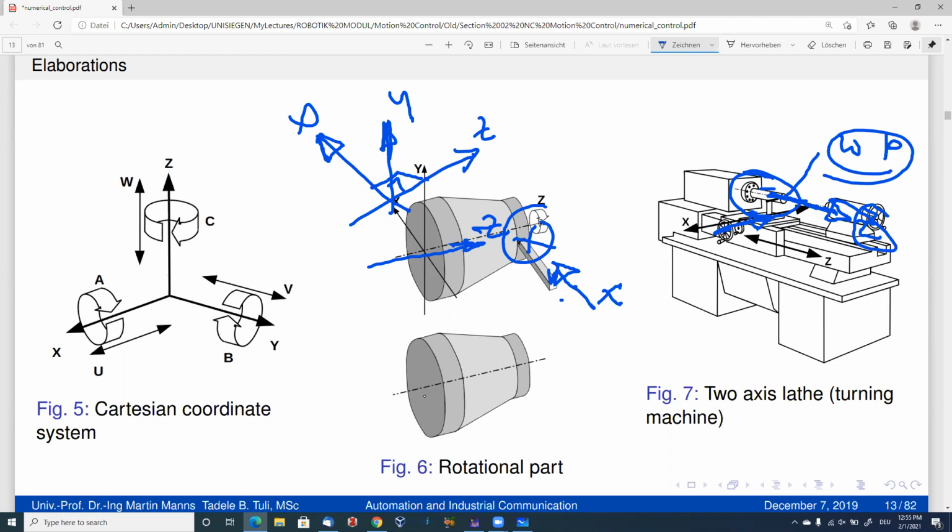The rotation about the Z axis is a rotation of the tool, or the rotation of the workpiece. Along X, there is a translational motion. This translational motion is called feed. If you have the speed, then it is called feed speed, or feed rate. The Y-axis is actually nothing for now. We don't have any job on the Y-axis. So that's a point here.